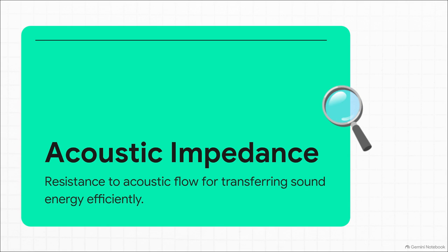Acoustic impedance. Simply put, think of this as the resistance to acoustic flow. The horn is basically acting like an acoustic transformer. Just imagine the intense, physical, high pressure pushing against a tiny speaker cone at the narrow throat of the horn. The horn's job is to efficiently transfer that high-pressure energy into the low-pressure open air of a large room. If you don't have a proper impedance match, it is catastrophic. The sound gets severely distorted, the diaphragm displacement goes completely off the charts, and the driver could literally break itself apart from the violent resistance.